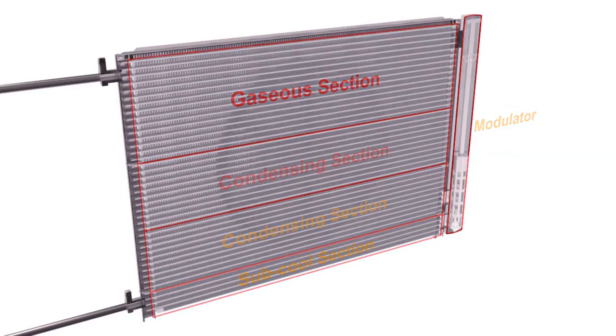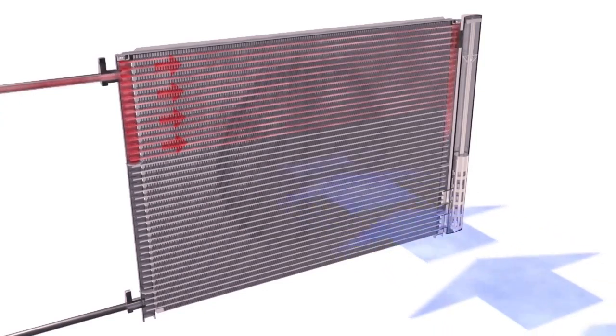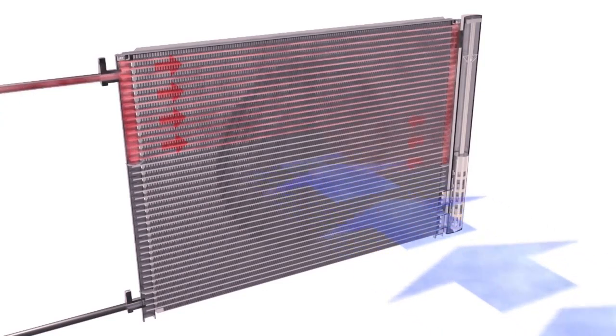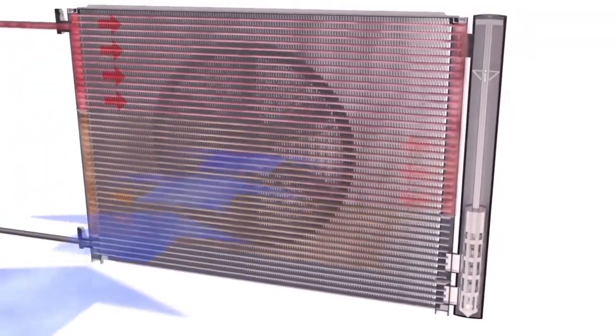The gaseous, condensing and subcooling sections consist of tubes and fins, and, as the refrigerant passes through the gaseous section, the heat contained in the high-temperature refrigerant gas transfers through the fins to the outside air.